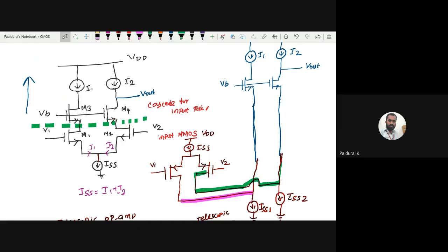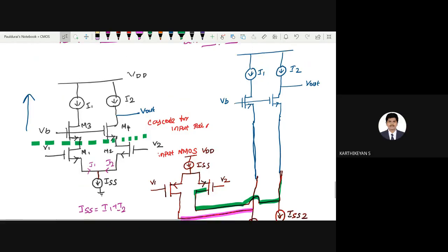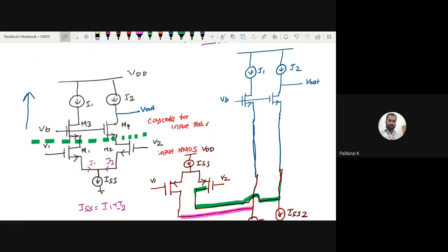No, sir. Now can I replace the I1 and I2 by suitable transistors? What will come? Very simple, I will replace them right there. Now listen to me carefully. What would these I1 and I2 actually be here? Actually this is my NMOS input pair. So who is the load device? PMOS, right?